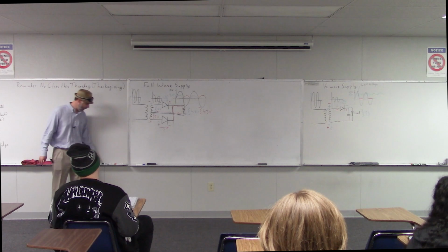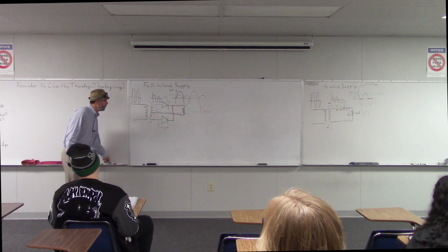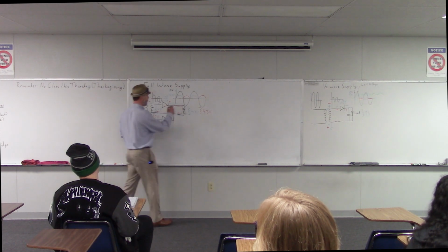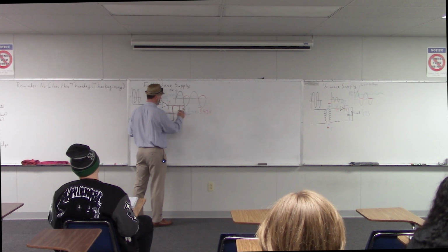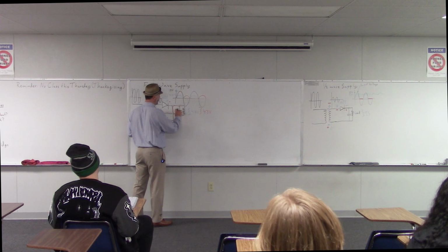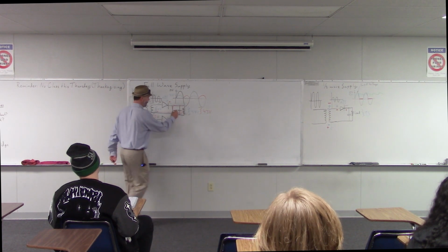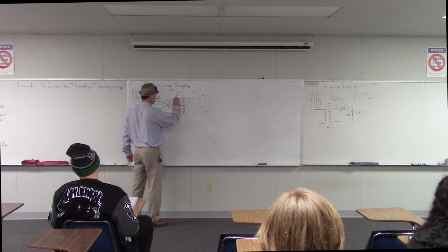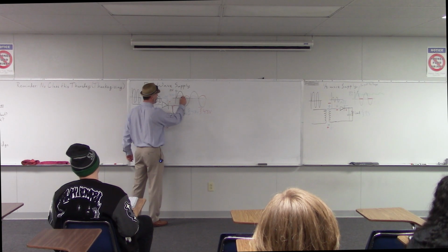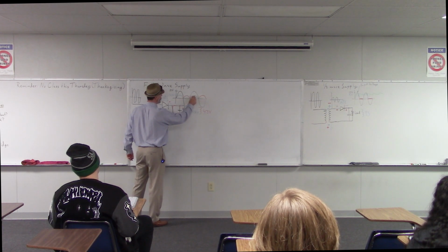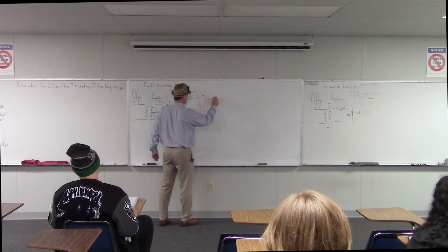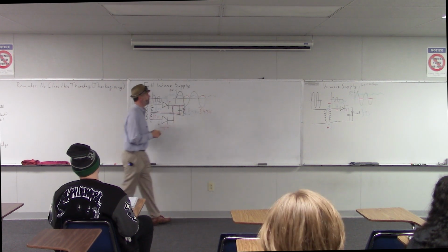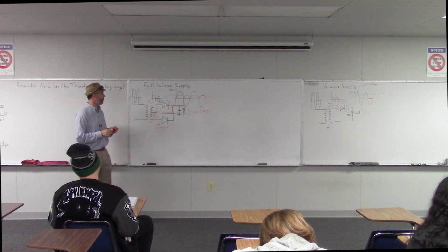All right. And then, yeah, again, if we were really building this supply, we would put a capacitor in parallel with our load, and that would help to smooth out the signal a little bit, so you would get kind of a smoother signal that looks something like that.